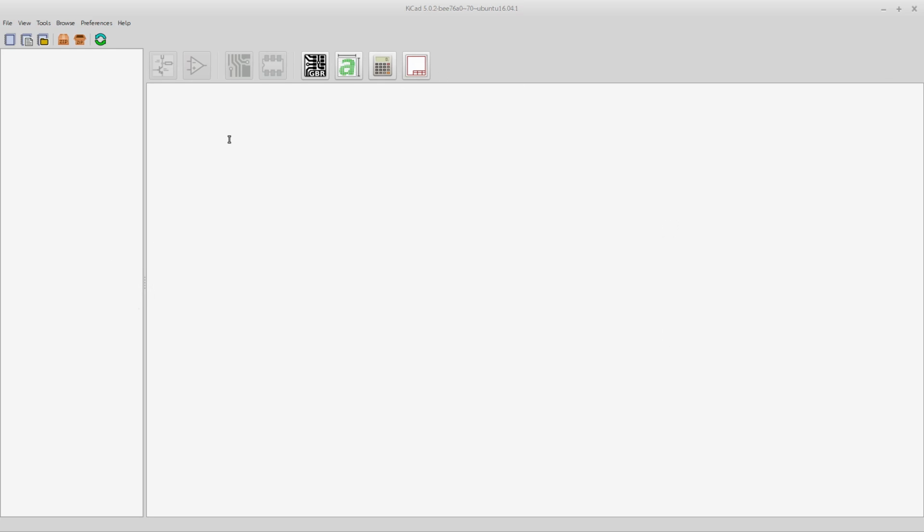This first window here is the container for the project. That's kind of what you want to think about. The project could be many pieces, and it will be many pieces. It's going to start out with your schematic and your PCB. Then you're going to get net lists in here. You might have some other libraries or library caches in here. If there are any pictures you want to put in, they'll be in here as well. And when you finally export this into Gerber files, the files that you're going to upload to the PCB board house, you're going to see all of those in here as well, and probably the zip file that you're going to make from all of those things. So a whole bunch of stuff is going to be in here. Remember, it is the project, and a bunch of other pieces.